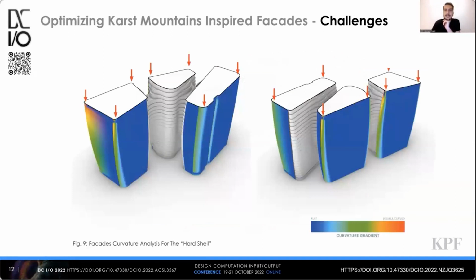So after generating the massing, what we have done was a very simple analysis of the entire facade. This is the most basic Rhino command that you can find, the surface analysis tool. And whenever we applied that after we generated the massing, we started to realize, hey, we have a problem at the corners, as we were expecting, obviously. In 80% of the building, as you can see, all the blue zones were flat or single curvature. However, the corners were the most problematic part.